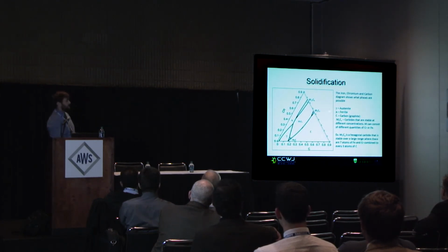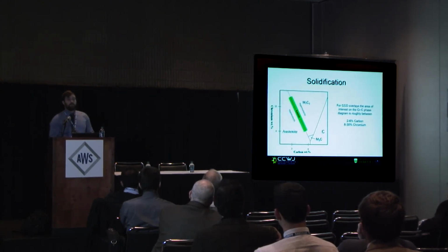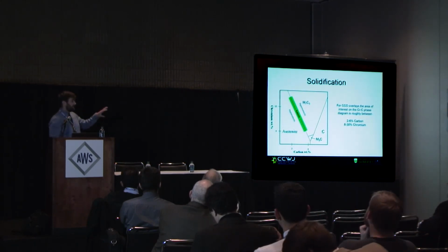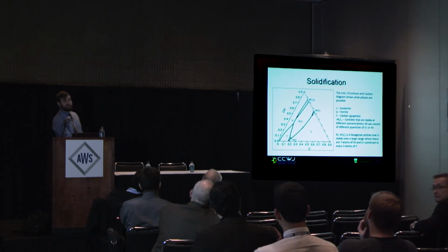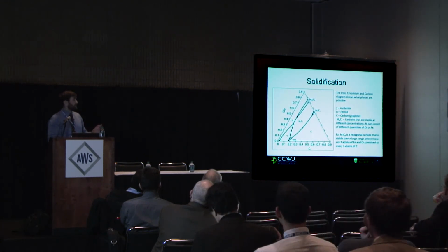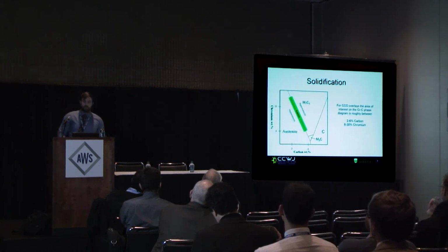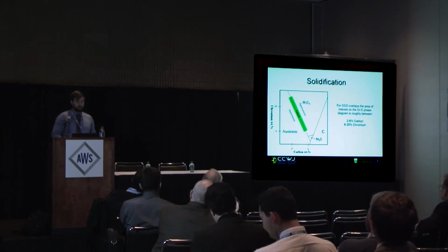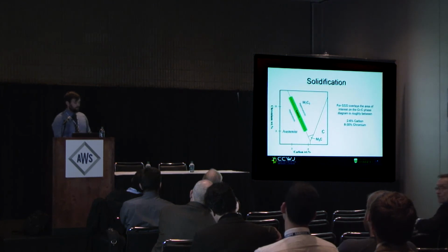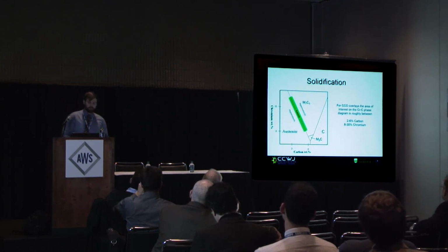Now, the most important is probably this M7C3. Luckily for us, we don't have to worry about the whole of the actual phase diagram. We can take it down and look at just this area, which is the only area of interest for us. With the commercially produced chrome carbide overlays, you find that they can fall anywhere in this range of carbon and chromium amounts.